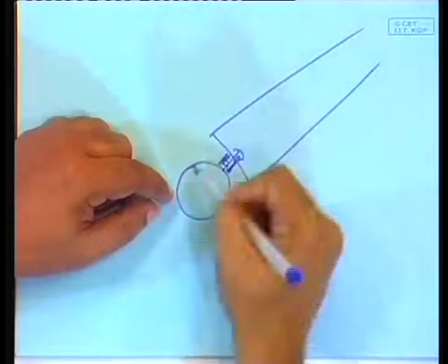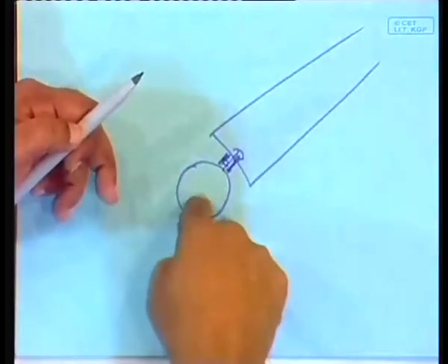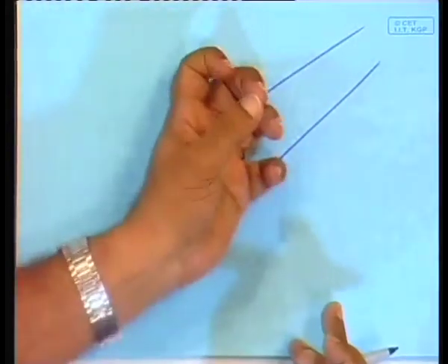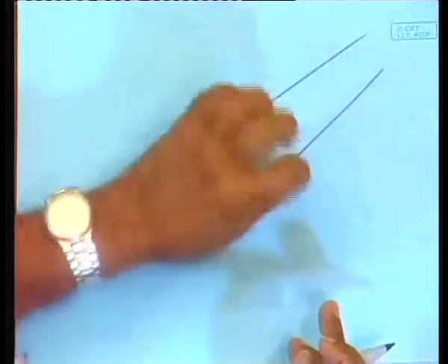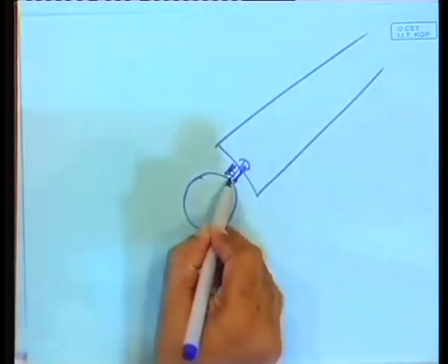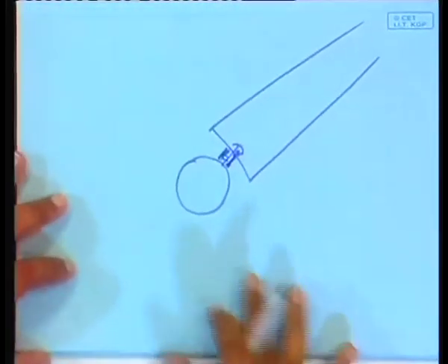Okay. So, these blades are not actually firmly attached to the axis. There is a scope for this to turn, okay, and that is the pitch angle control. So, at these points there would be motors, servo motors doing this turning business. What will the logic be?